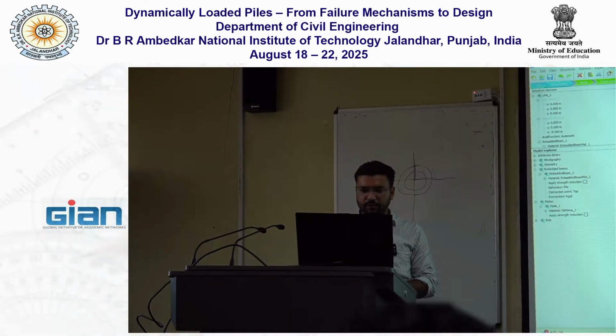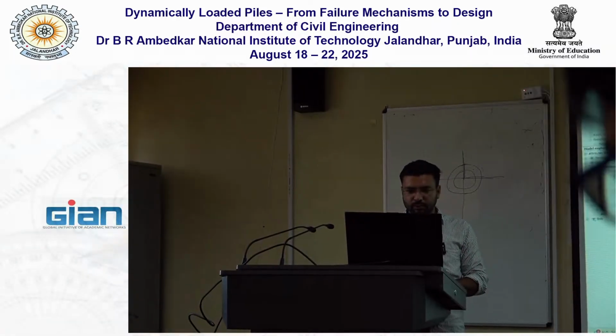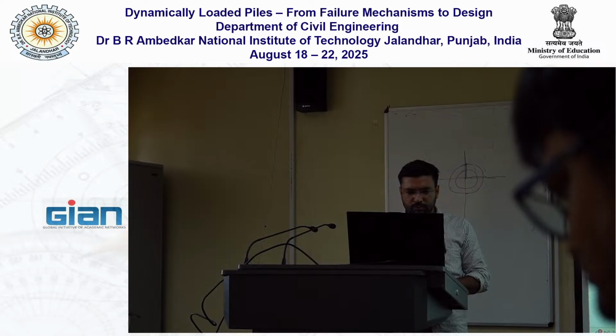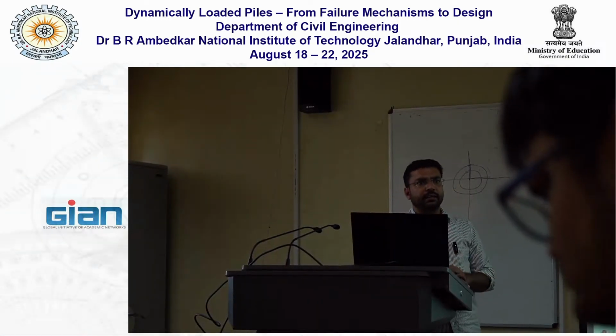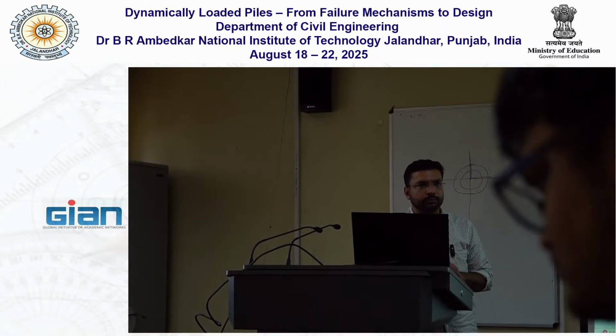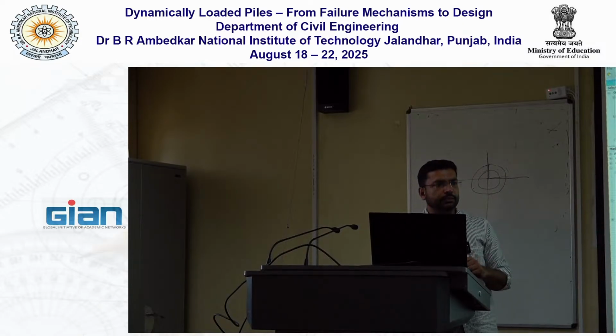Diameter like 0.150. In order to get the skin friction in the embedded beam, you have to assign some values. Otherwise it will not show any skin friction.